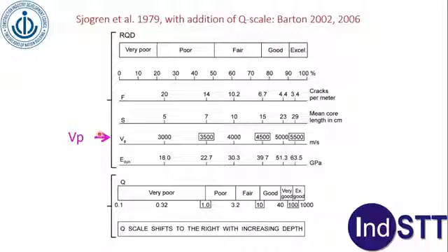So this is the elevation again. And here, for example, this was done across a known drift location. So this is a drift location here. These are different studies for finding water lenses or fracture zones. Cavity detection. So this is again a cavity here. Depth can be as high as 500 meters. So this is one investigation which we have done where 500 meters of depth was investigated using ERI. As I said, it can detect boulders, zones of water accumulation, etc.